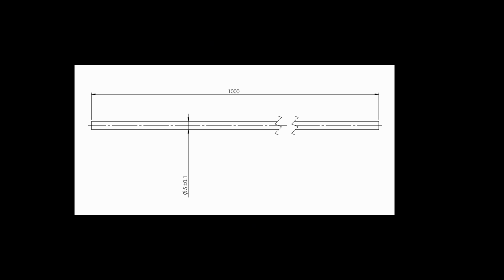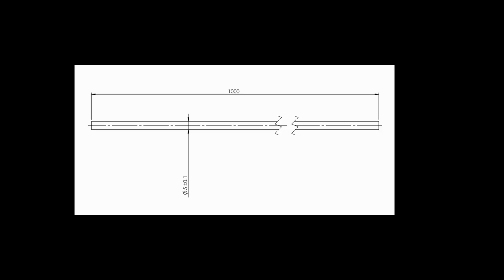So as this 5 plus minus 0.1 mm diameter is a regular feature of size, GD&T Rule 1 will be applied by default. Meaning this 1 meter, 5 mm diameter mild steel rod can bend only 0.1 mm throughout its complete length of 1 meter, which is not practical to manufacture. So we have to mention that here GD&T Rule 1 is not applying. Something like this.